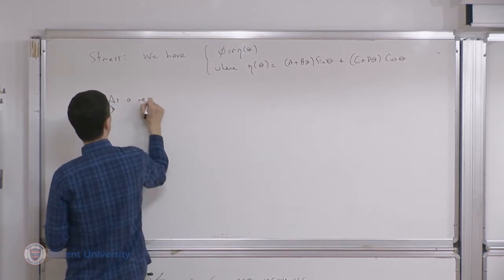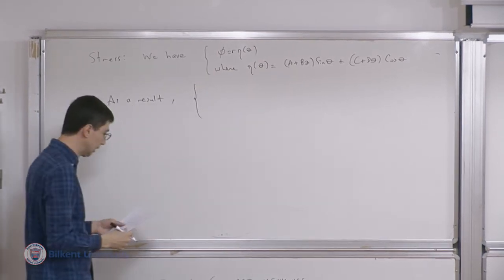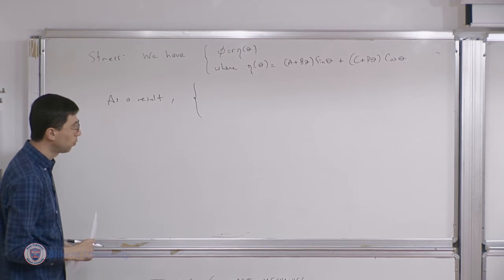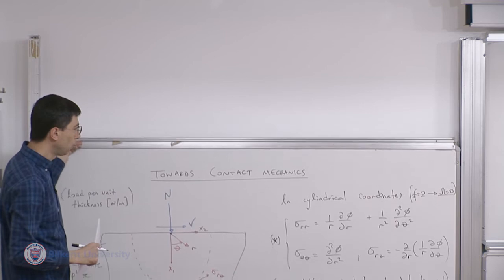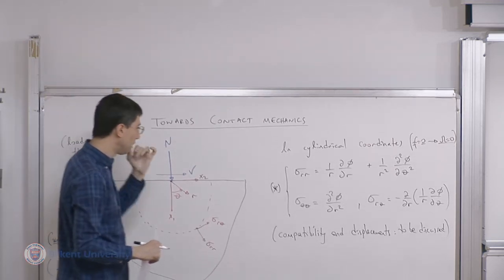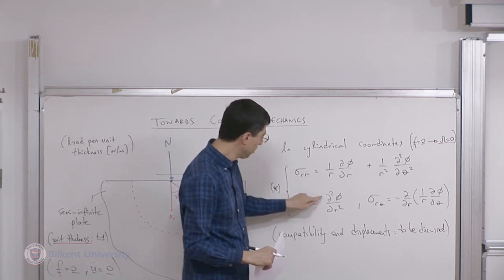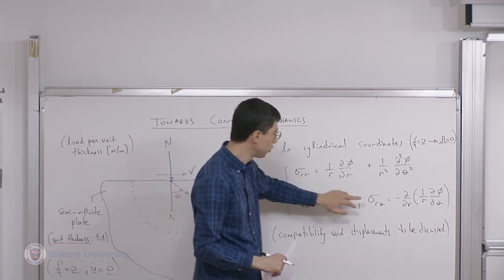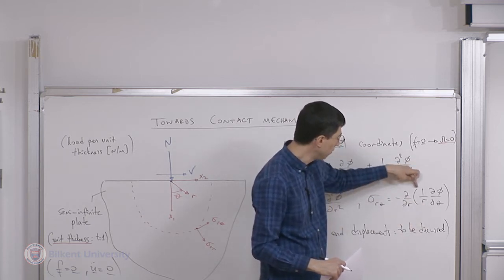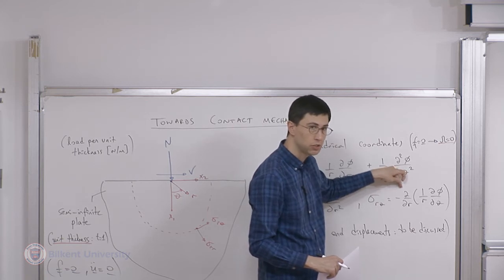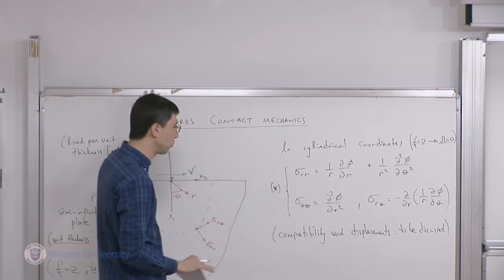Now, the simple part is, actually, I could have already written this before, and I'm going to pull up the board quickly here. So if you look here now, phi is r eta. Second derivative with respect to r vanishes. And you take 1 over r. This is independent of r. One more derivative, it vanishes. So sigma r theta and sigma theta theta are 0 from the outset. Okay, I don't have to worry about them.